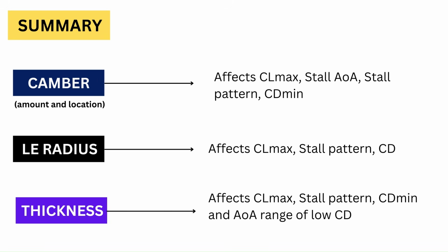While selecting an airfoil, we can get an idea of how a particular airfoil might behave by looking at its overall shape. Of course, these are general principles and have exceptions. So it is always better to look at the airfoil plots before making a decision. One benefit of using this information is we can now be better at shortlisting possible airfoils and don't need to look at a lot of plots. One very important parameter not discussed in this part is the moment coefficient, which should be considered to make the design stable and reduce trim drag, but that is a topic for another video.